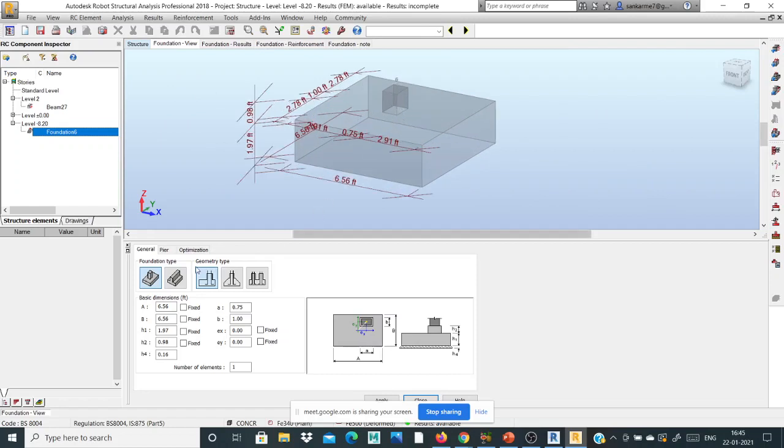Not only spread footing, you can go for slab footing, combined, eccentric, or any footing, and you can design them in Robot Structure also, right? I analyze a normal spread footing. This is a fixed width and fixed depth. I will fix this, same, I take this fixed depth and fixed width. The eccentric is 0. If you untick this eccentric, automatically the column comes into one corner, right? For the eccentric footing, you provide the eccentric distance for this column. Once you click this, automatically apply, right?